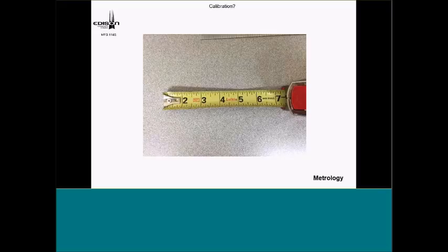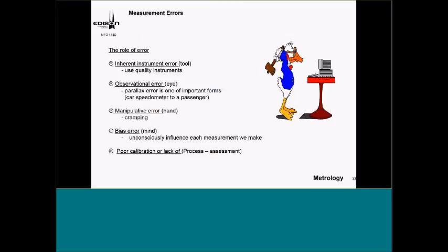I'll tell them from now on, no matter what instrument we use in this lab, you check the calibration. As I lecture, I talk about calibration pretty heavily, whether it's an outside micrometer, a depth micrometer, vernier caliper, et cetera, so on and so forth, Johansson blocks, gauge blocks. I show them how to check calibration. And for a 6-inch scale, they may ask me, is this calibrated? And of course, I'll tell them yes. So I have a lot of fun with that, and they don't forget it. So again, calibration is a comparison to the higher standard, the test for accuracy, and they just don't forget it.